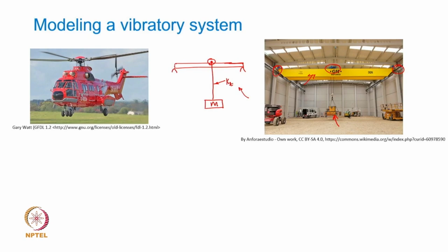So, if I assume the rope to have a stiffness given by a variable Kr, and if this girder is assumed to be a simply supported beam, I can now treat the stiffness of this beam as defined by a spring. Okay. The spring basically defines the stiffness of the beam, and I will call this Kb. So, if the force gets applied here, this beam might deflect like this, and the mass will of course deflect, and it might further deflect because of the deflection in the rope. Okay. So, I have one stiffness here, that of the beam, and another stiffness which is the stiffness of the rope, which will carry the mass ultimately at the end. Okay. So, this is a simplistic approximation of this entire system.